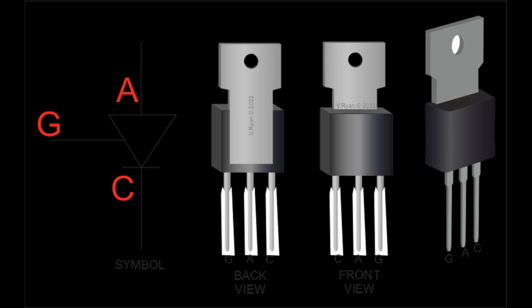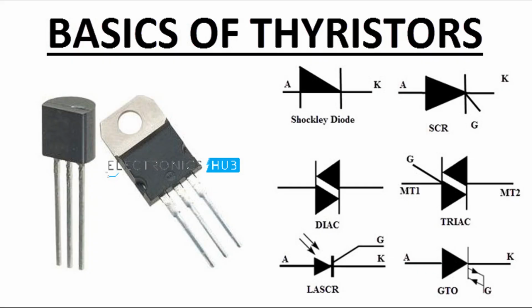Applications. Opto-isolation. Used in circuits requiring electrical isolation between the control and power stages. Remote switching. Suitable for remote control applications where electrical signals might not be feasible. Overvoltage protection. Provides protection by triggering in the presence of excessive light, e.g., lightning strikes. AC and DC power control, employed in various power control applications where optical triggering is advantageous.